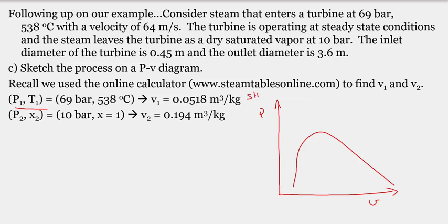So this was the superheat, which is up here, right? It's at the high pressure or high temperature conditions. And remember, we always want to put those isotherms, those constant temperature lines, on all of our diagrams. So I'll put a couple of those on here. And we learned at the exit state that we had a lower pressure, and we had a saturated vapor. So the easier point for us to put on the PV diagram is actually this saturated point. So let's take this lower temperature condition here, and we will call this state 2.